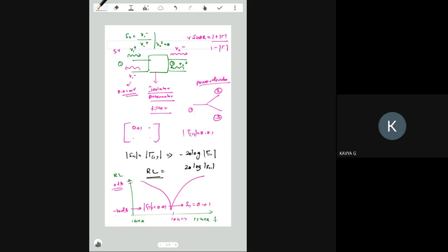So now our focus is S parameters. We have seen one out of 4, and what is the use of S11, which is related to the return loss, for more practical coefficients. If you take, for example, an isolator, they don't give an S11 value, they will give return loss. That doesn't mean that S11 is not known, basically.